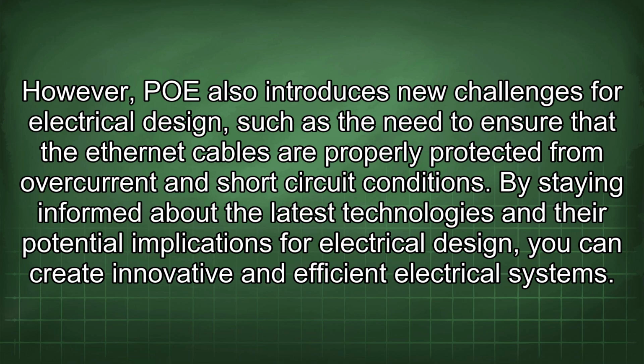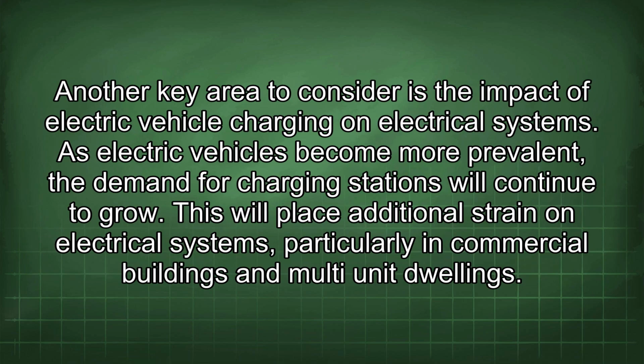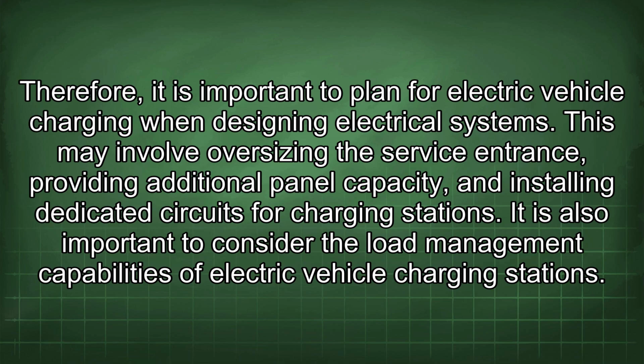Another key area to consider is the impact of electric vehicle charging on electrical systems. As electric vehicles become more prevalent, the demand for charging stations will continue to grow. This will place additional strain on electrical systems, particularly in commercial buildings and multi-unit dwellings. Therefore, it is important to plan for electric vehicle charging when designing electrical systems. This may involve oversizing the service entrance, providing additional panel capacity, and installing dedicated circuits for charging stations.